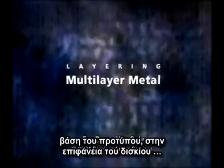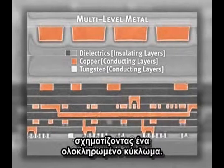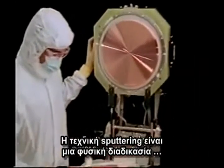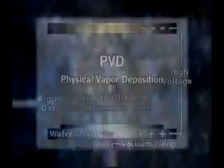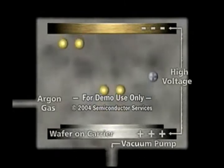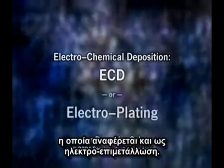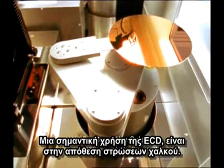Metal layers, deposited and patterned on the wafer surface, are used to connect the individual components, creating an integrated circuit. The most common deposition technique for metals is sputtering. Sputtering is a physical process and a form of PVD, physical vapor deposition. Sputtering is similar to freeing pieces from a concrete wall using a sandblaster. Another method of depositing a metal on the wafer is electrochemical deposition, ECD, also referred to as electroplating. An important use of ECD is to deposit copper layers.